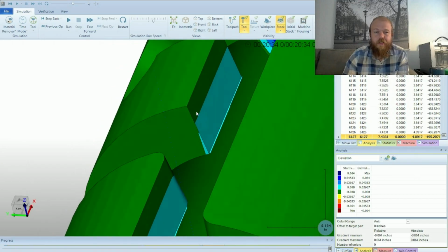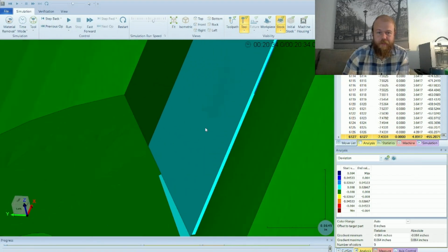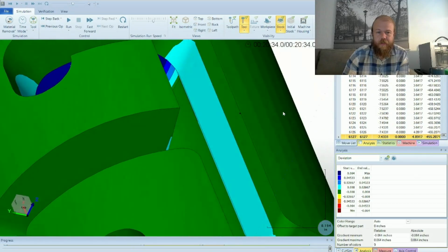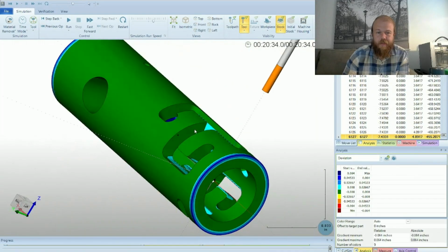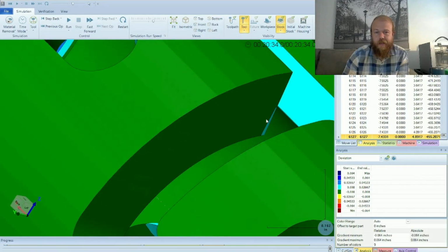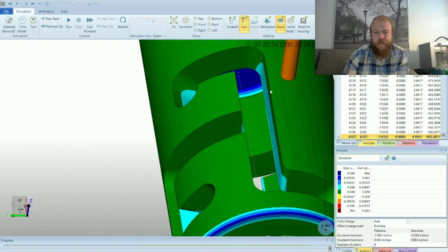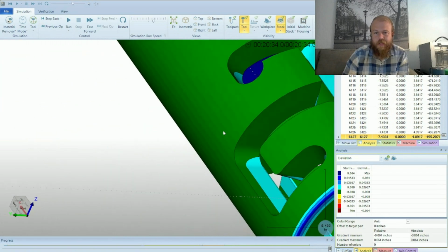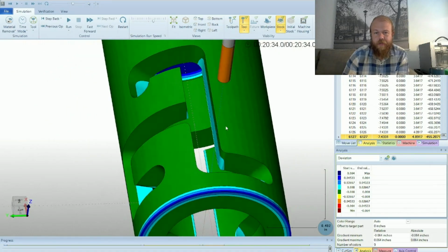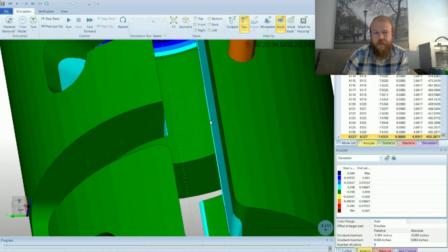So if I see here, everything in green is cut to size with a cut tolerance of plus or minus 0.008 of an inch. If I zoom in, I can see this light blue color along all of the sidewalls of the pocket. Well, not all of them. I can finish this up as I'm going in this linear move, but I guess you could say like vertically, and then horizontally, I'm not able to get to the bottom because I'm not able to offset for the tool.